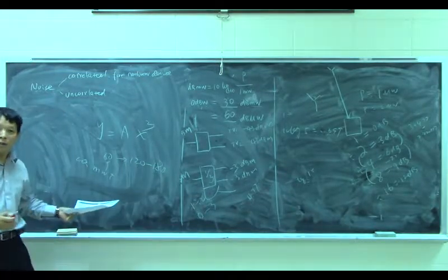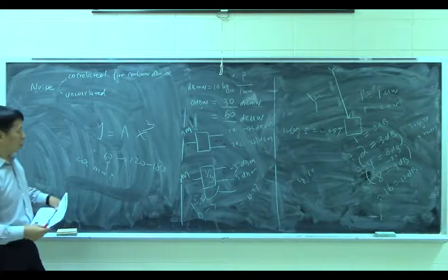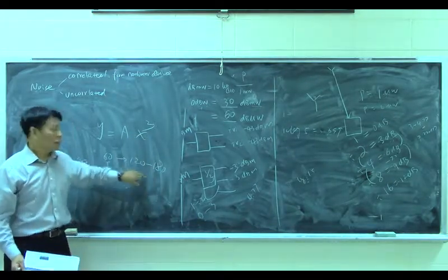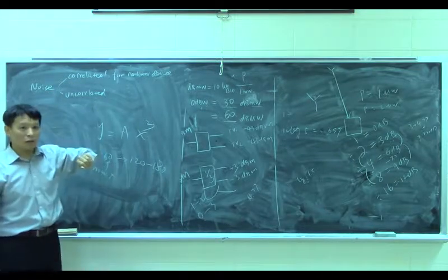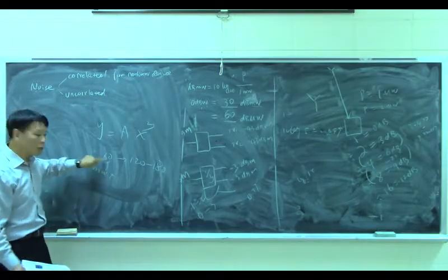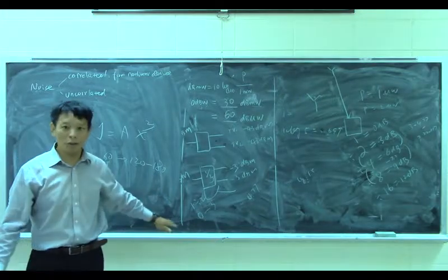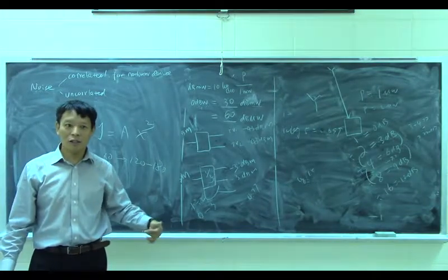So that's the harmonics. Because the circuit is not linear, we are going to have this. This gives us noise. This is called correlated noise. That means if you have the input, you always have this noise. You cannot remove this noise because your circuit is not linear.